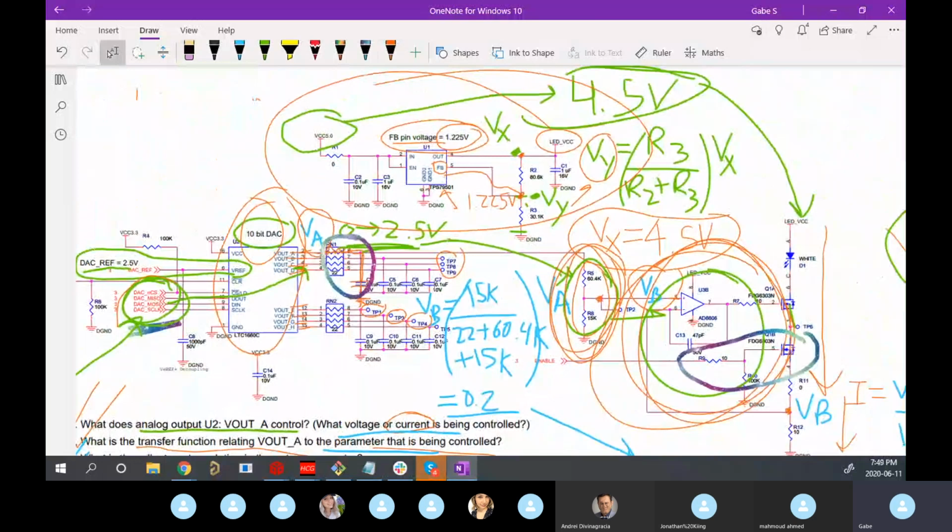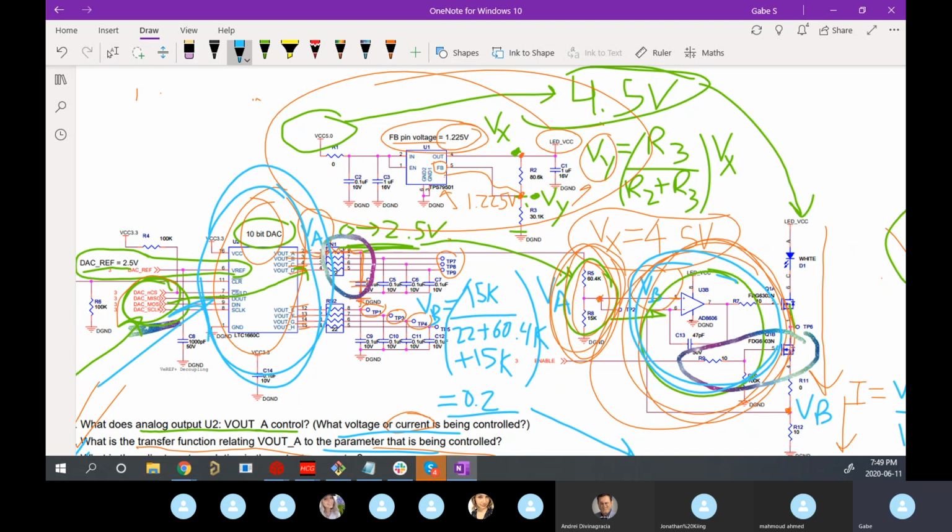That's a good question. I don't think we have any constant current circuits, for example. There's none of this on the right. We have a DAC on our car, right? We use that to control the throttle for the inverter input. So we send digital to the DAC, and that sends an output voltage to control our motor. We have linear regulators to generate different voltage rails. We have a bunch of voltage dividers. We have filters. We have test points. We just don't specifically have this constant current guy at the end.